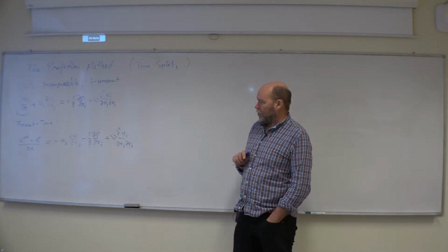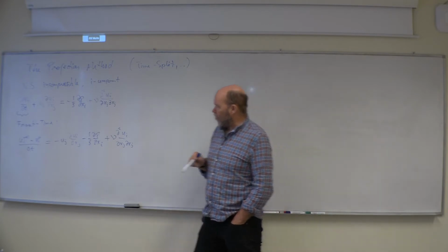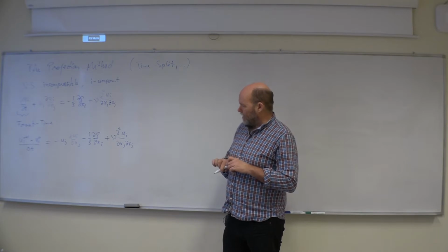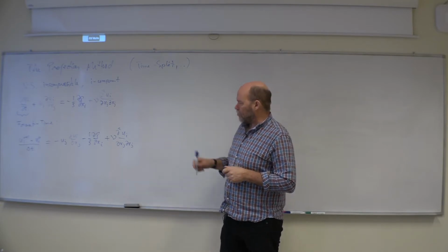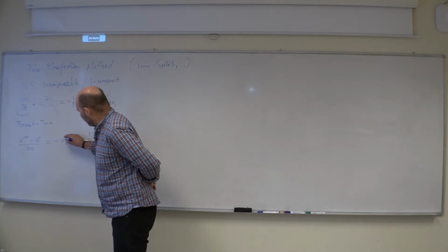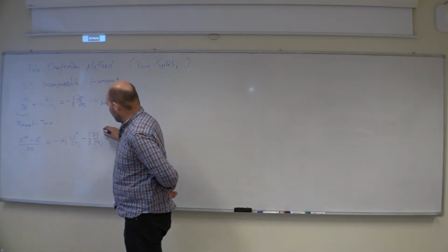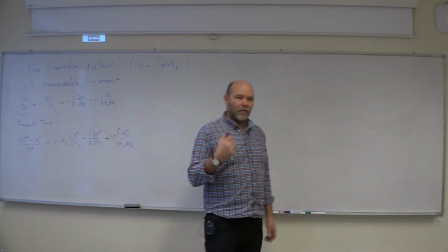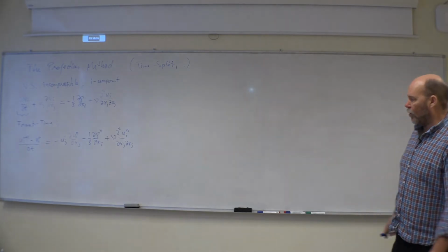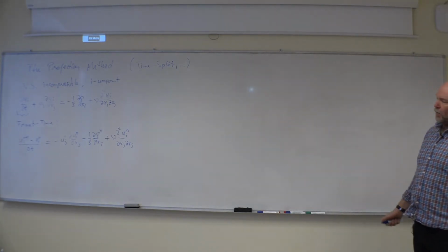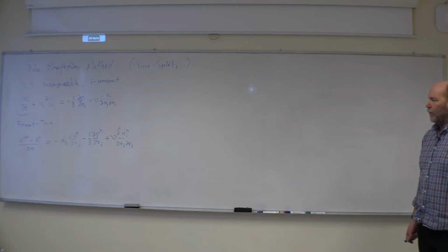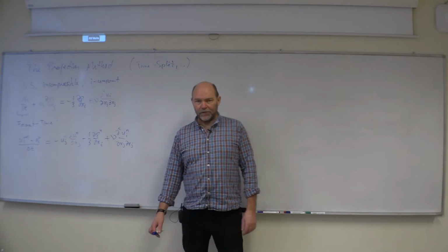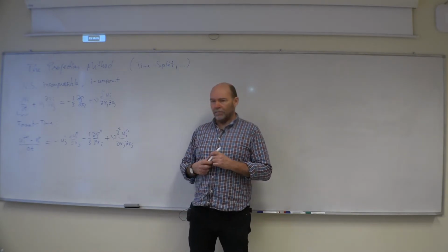Now, according to this forward time first order Euler time step, everything on the right hand side should be old values. Time level n: the pressure at time level n, the velocity at time level n. There you have an explicit scheme, no problem. You can find the new velocity at time level n plus 1 because you know everything, pressure and velocity at time level n. No problem. But this will be wrong, sadly.